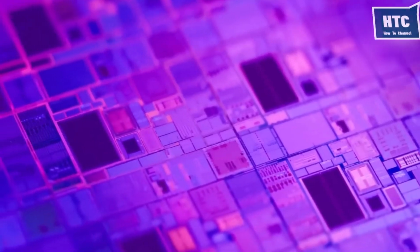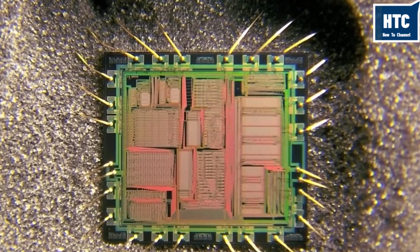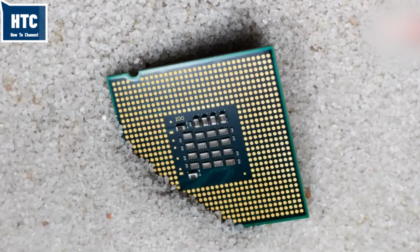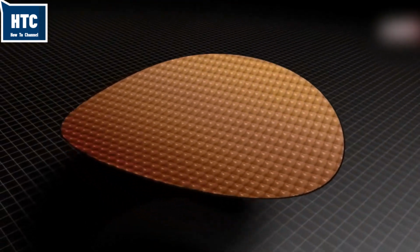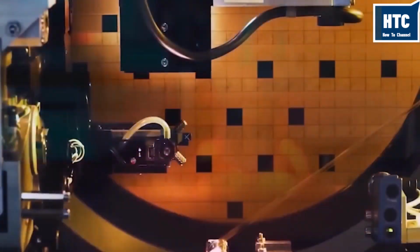Only then does the physical journey begin. It starts in the Earth's crust. We mine silica sand, or silicon dioxide, SiO2. But to build a brain, we need purity. The sand is heated to 2,000 degrees Celsius in an electric arc furnace with carbon, triggering a chemical reaction that releases the oxygen as carbon dioxide, leaving behind metallurgical-grade silicon.